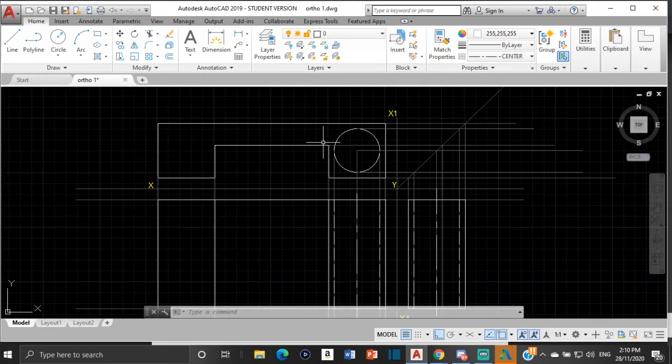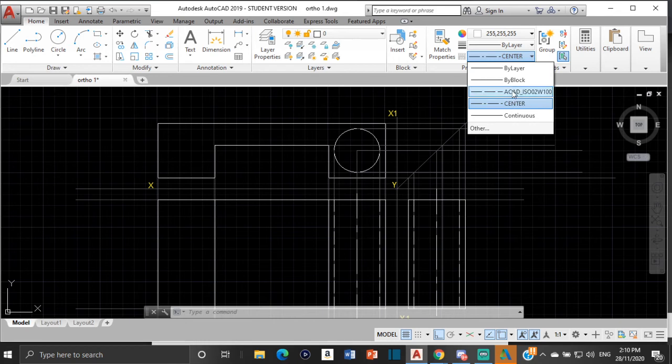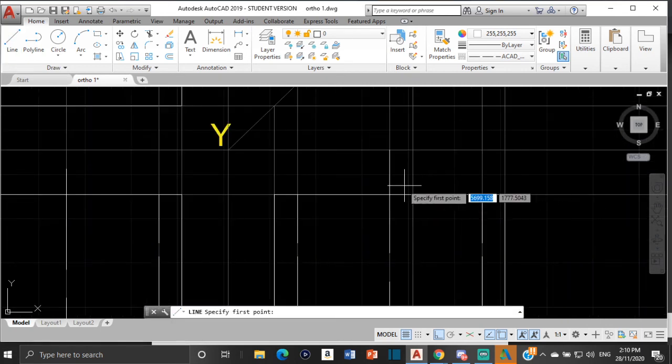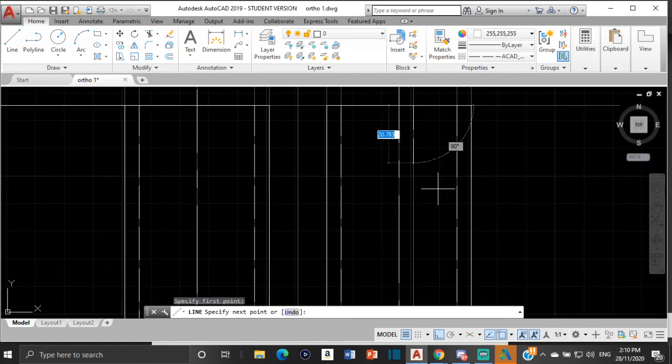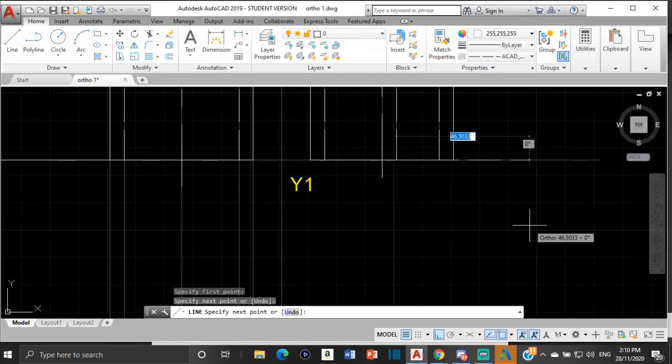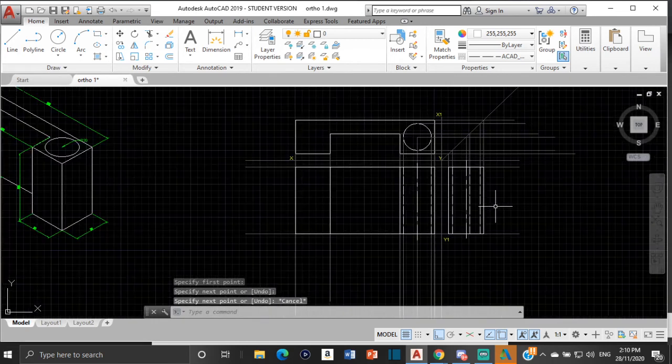So it goes across here, meets this 45-degree line and comes down. So from there, we have to represent that using broken lines. Alright, so this line here goes across from there to meet the 45-degree line and goes down. Let me click on that and then close that off right there. So that's my drawing completed.